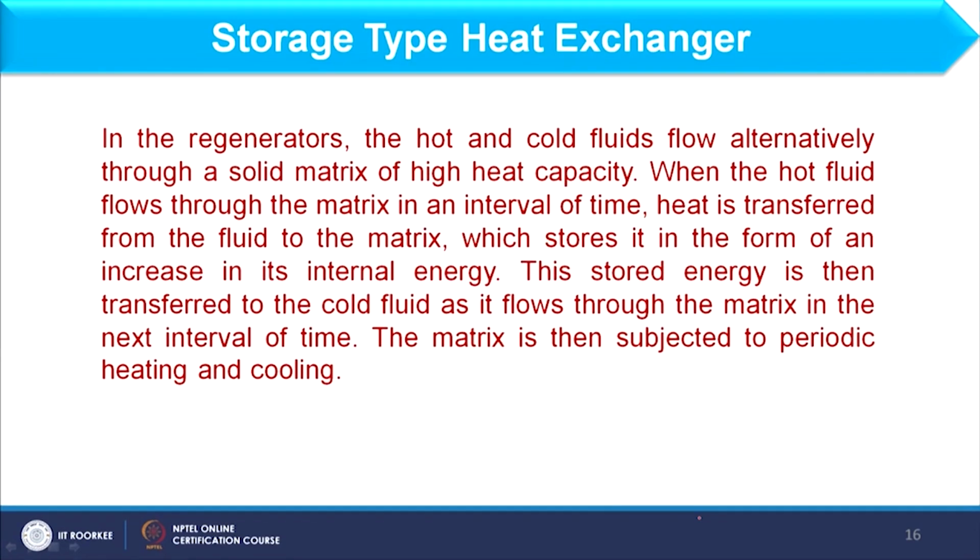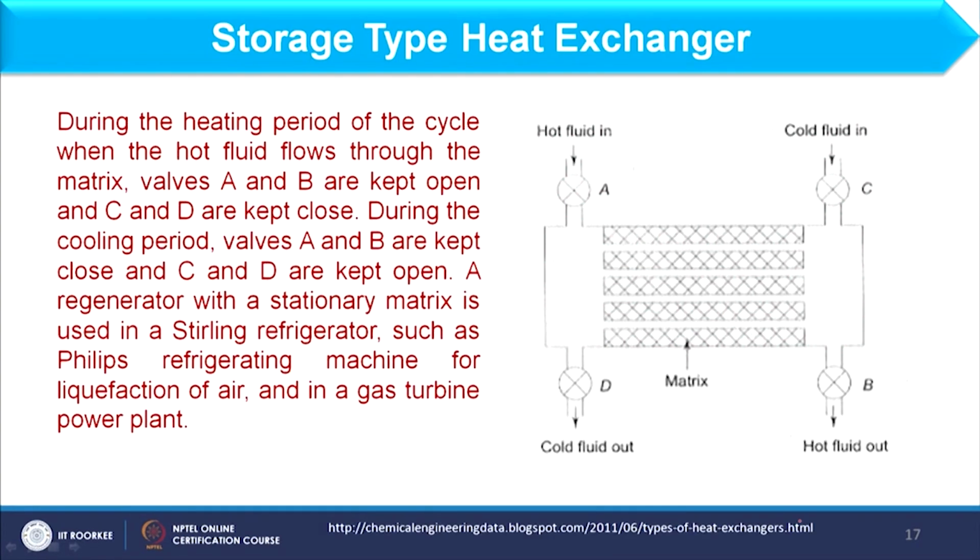Storage type heat exchangers are basically called regenerators, where hot and cold fluids flow alternately through a solid matrix of high heat capacity. To illustrate that, let me focus on this image. Here in this heat exchanger we have the solid matrix, a zigzag formation. This is the solid structure, or we can consider that as packing.